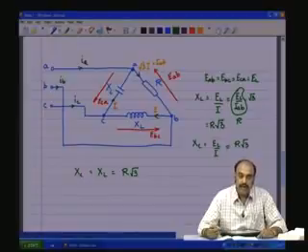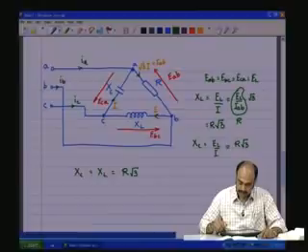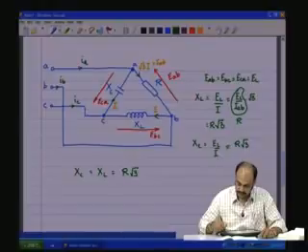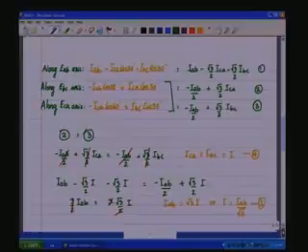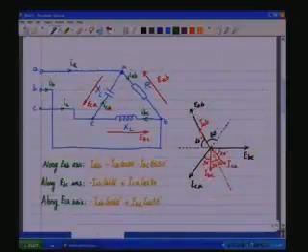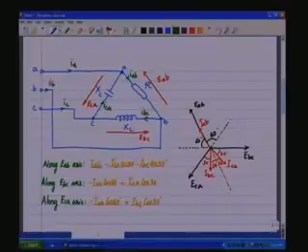And if that is done, then automatically you will have the currents flowing here as root 3 I and I, and they will be balanced when looked at from the point of view of the equivalent phasor diagrams, because equivalently if IBC is equal to I, ICA is equal to I, then what flows through this, and what flows through this will all be equal.